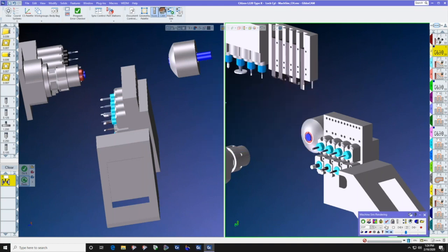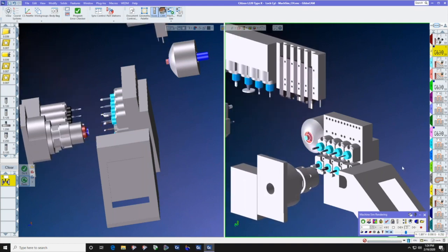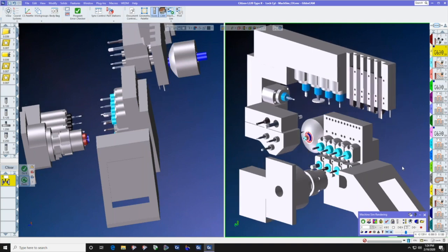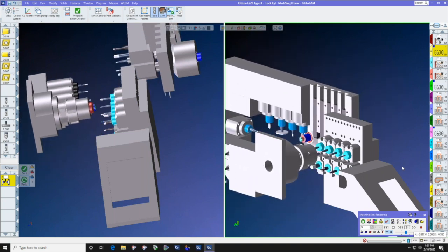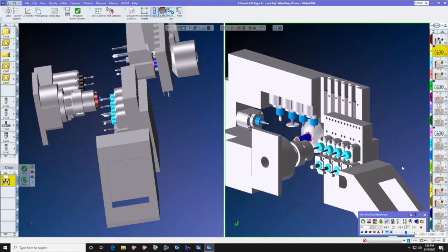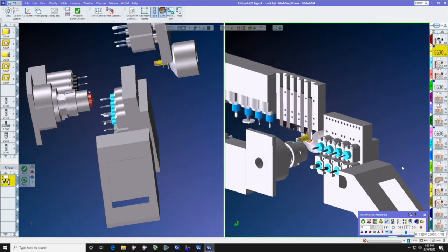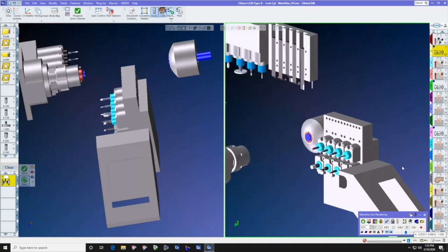Automatically, when we do a cutoff part transfer, you will see that the appropriate axes physically get out of the way so that the sub spindle can come in, the parting tool can do its job, and nobody has any collisions. Again, this is a function of MTM level 3. So MTM level 1 was a single flow machine, MTM level 2 was a dual flow machine, and MTM level 3 could be 3 or more flows, and they're not treated any differently. So if you can program a 2-flow machine, you can program a 5-flow machine.